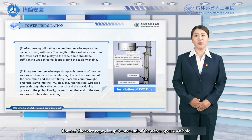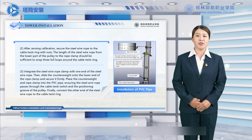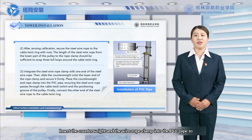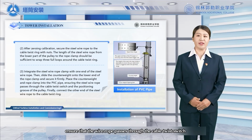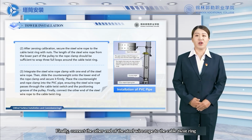Connect the wire rope clamp to one end of the wire rope as a whole, and then insert the counterweight into the lower end of the wire rope clamp. Firmly fixed. Insert the counterweight and the wire rope clamp into the PVC pipe to ensure that the wire rope passes through the cable twist switch and the pulley positioning groove. Finally, connect the other end of the steel wire rope to the cable twist ring.